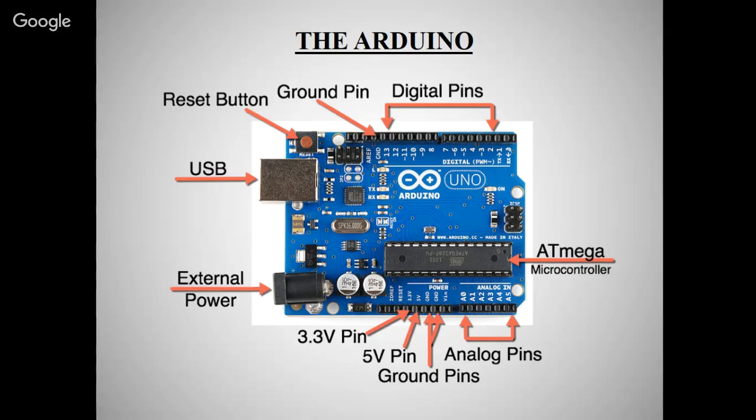If you want to control the brightness of an LED or the speed of a motor, then you have to generate PWM on the pin. Whatever the voltage of the motor, like 24 volt, 48 volt, any type of motor you want to control, you can generate PWM at these pins.